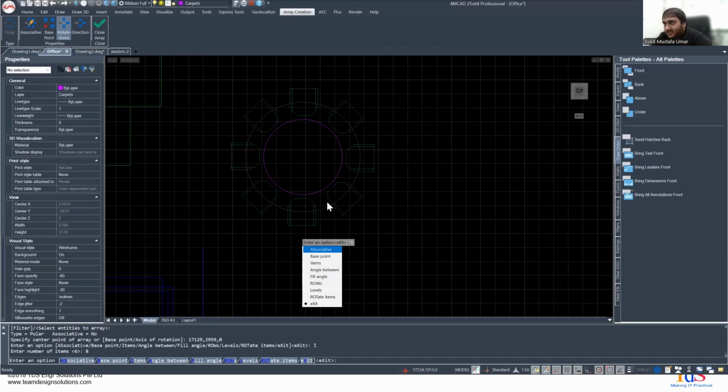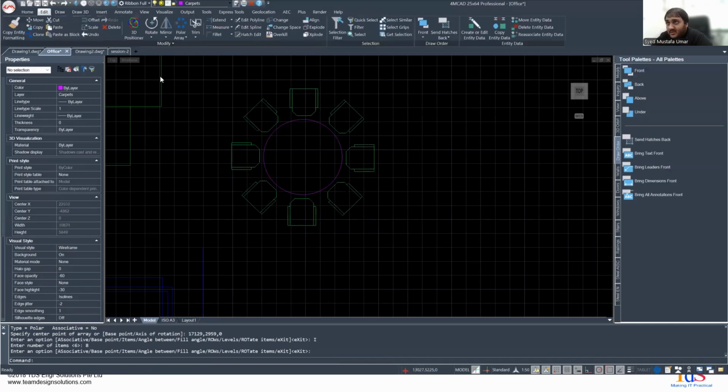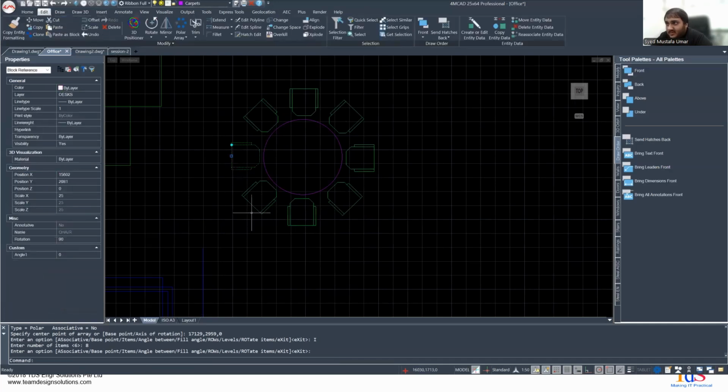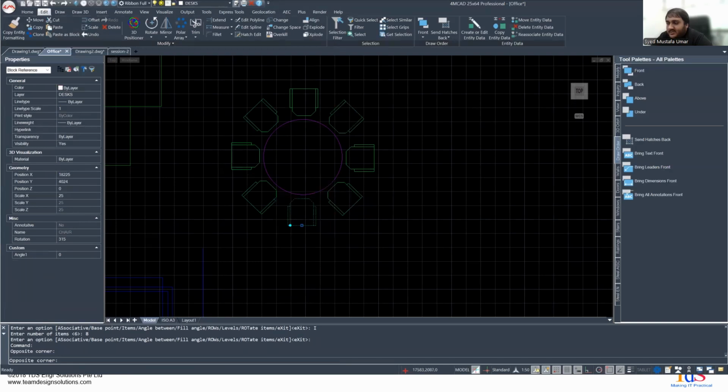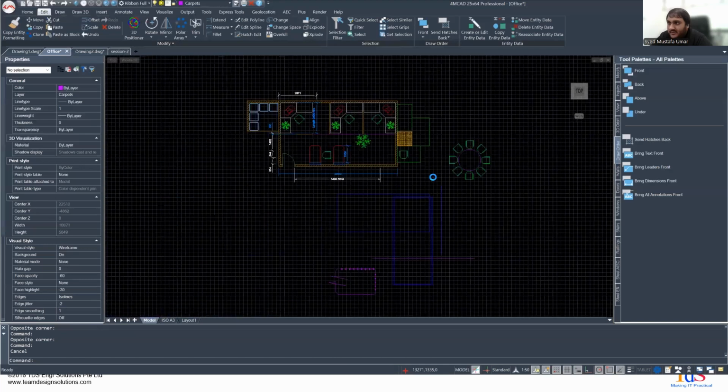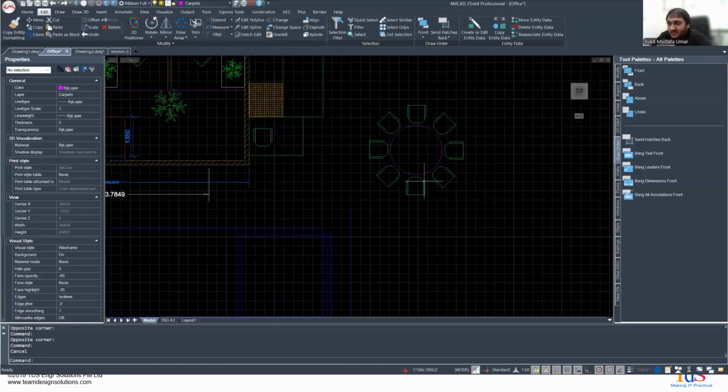It's a very powerful tool, and I can go ahead and close the array, and depending on what setting I've kept, all of these will remain as block references. I can also have them stored entirely as one object, as a sort of array object, but I've chosen not to do that right now. But this is just for you to keep in mind. If you're trying to build something, this is very useful. Saves you a lot of time.